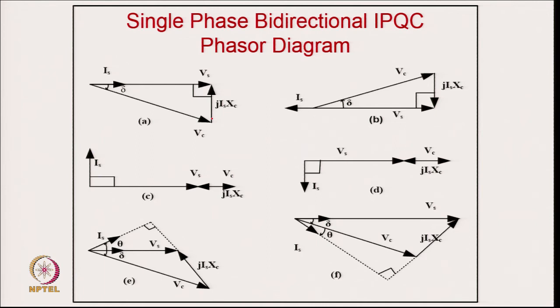Okay. So, with voltage here, the current is out of phase, meaning power is negative, and in this case also you have a drop which is perpendicular to it, it will be just this, and then this will be the Vc. So, here is how we discriminate between rectification and inversion. This we can consider symmetrically to a synchronous motor. For a synchronous motor, delta is always negative, and this is the induced EMF corresponding to the synchronous motor. This is the synchronous generator, where the induced EMF is always leading.